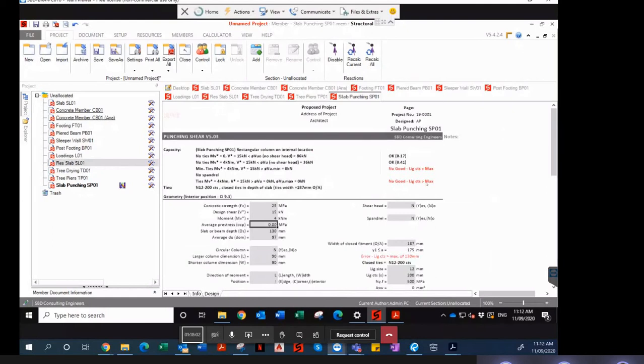And the other thing which happens is, if you've got a steel column, obviously you have a large load, so you put a pad footing or a bored pier underneath that. But if it's a timber stud, the timber stud is actually sitting on a bottom plate, and that bottom plate also helps you distribute the loading.